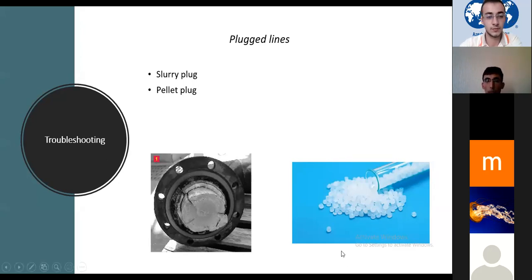And once this emergency also happened. After extrusion, we sent our pellets with air blowers through the pipes to the bagging area for packaging. And once the compressor set value was high, like 1.4 or 1.5 atmospheric pressure, higher than normal. Normally 1.1 or 1.2 bar is enough for transfer.